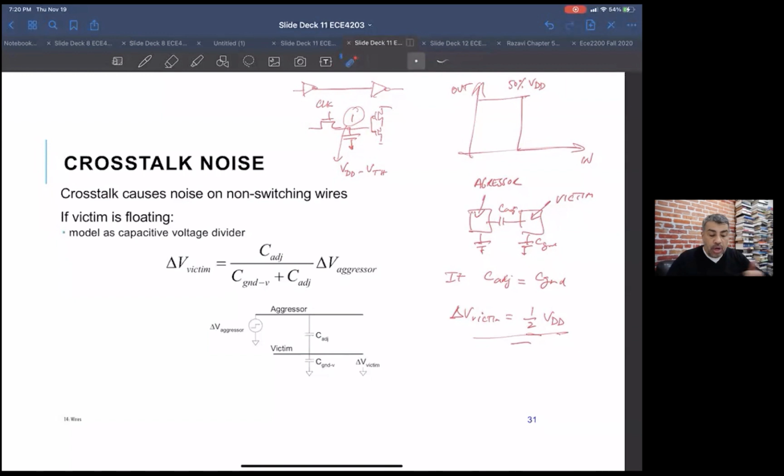If you can, you don't want them, and if you have them, you really want to shield them with a sort of metal cage. Sometimes in our analog circuits, we have to have floating nodes for sample and holds and other circuits. So we build these really tiny Faraday cages around those floating nodes with different metal layers, et cetera, to shield them from noise.